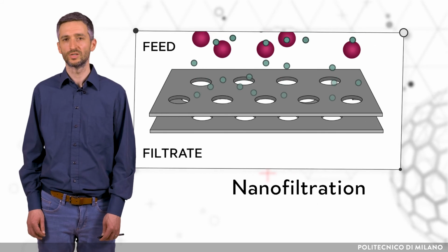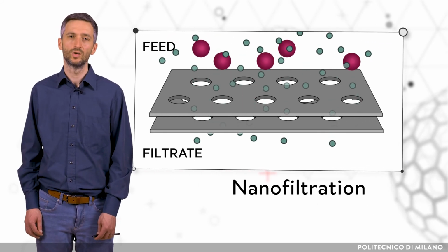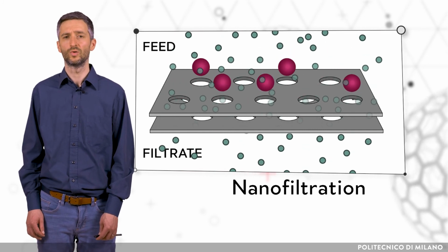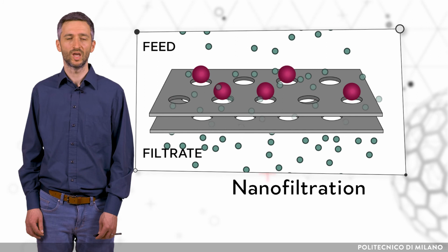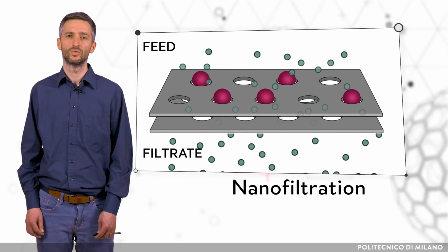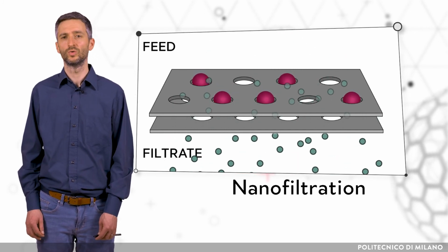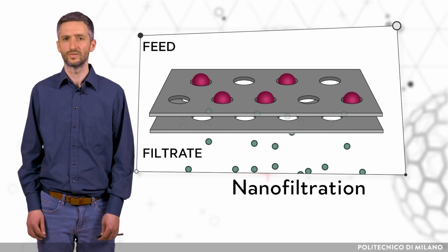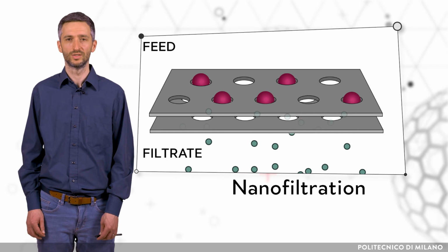Nanofiltration is a process based on the use of membrane filters with a selected molecular cutoff to remove larger molecules from the feed water. It can be efficient for uranium, as uranyl complexes predominantly found in water are usually larger than the typical molecular cutoff size of nanofiltration membranes.